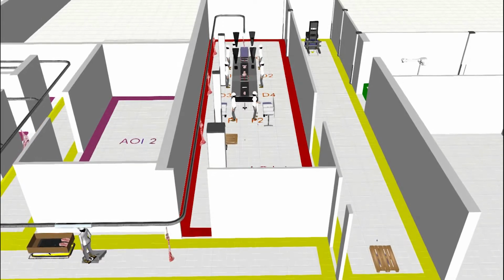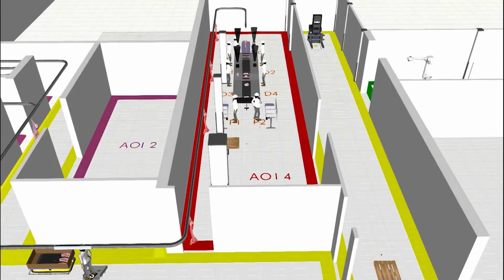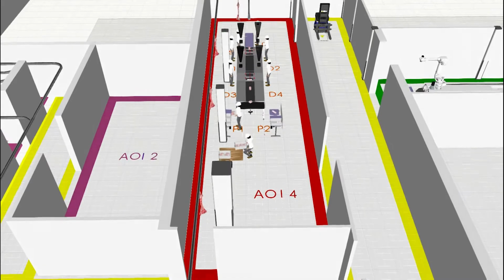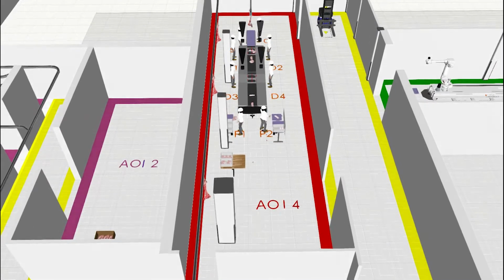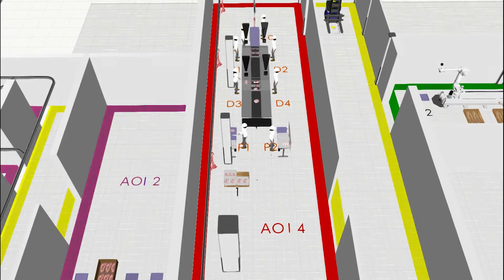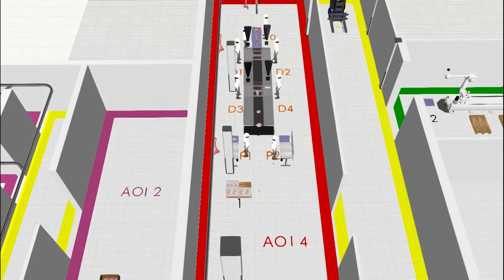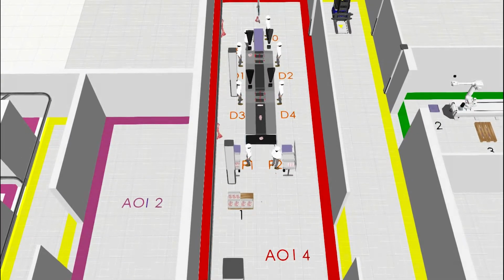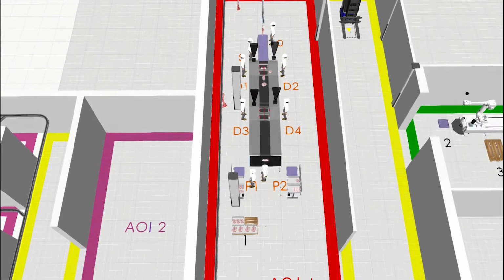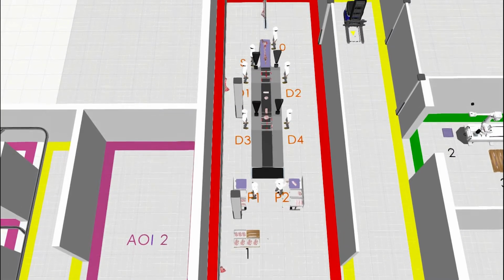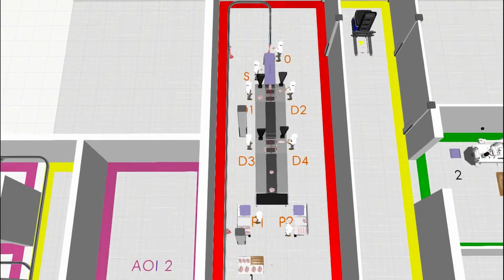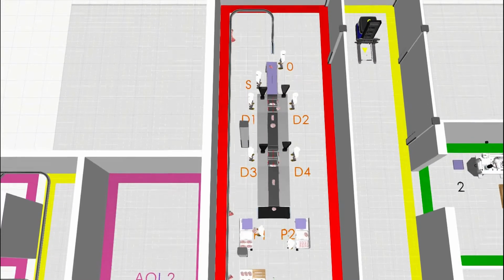At the pick-up position, the AGV takes the cart according to information about process completion, which is transferred from the production workers to ERP. At the predetermined drop-off positions in conservation chambers, the AGV automatically releases the full cart, moves back to the pick-up position and hooks the next cart. The AGV could be programmed to stop at the pick-up position, or an operator can call an AGV to a location using a push-button call box. Towing capacity is up to 1,000 kilograms.